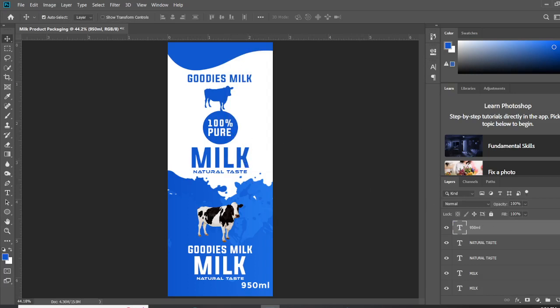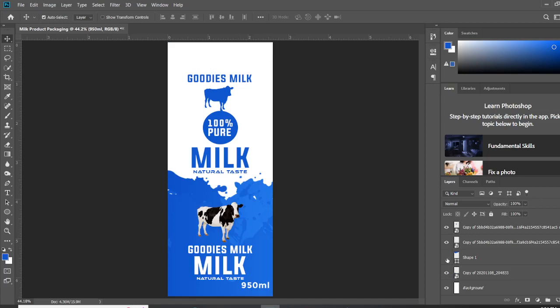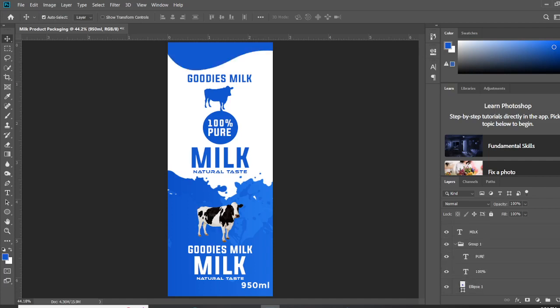So what I'll be doing is that I'm gonna scroll down, and I'll be leaving just this shape here. You can see I'm gonna toggle it on back, and the other shape, this one. So the rest, let me just kind of group the rest. So to select everything at once, once I select the first layer here, I'm going to come down to the last one I want to select. While holding my shift key, I'll click on it, so everything has been selected. Now I'm going to group this. I'm going to click on Ctrl G to group it, so everything is now in a group. I can now just switch it off like so. You can see, to toggle it off by clicking on the eye icon here to switch it off.